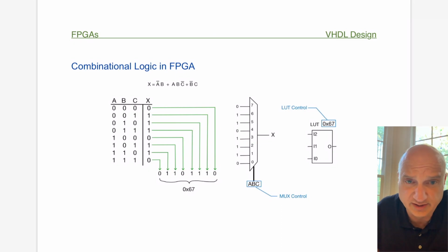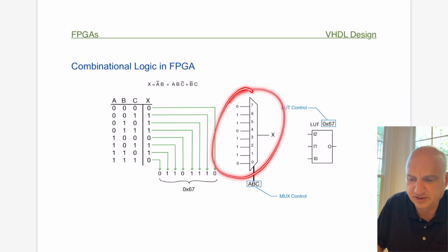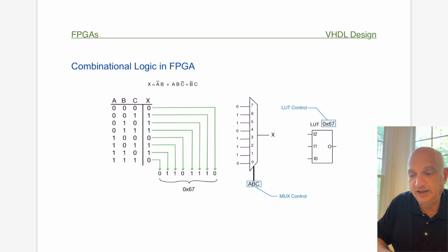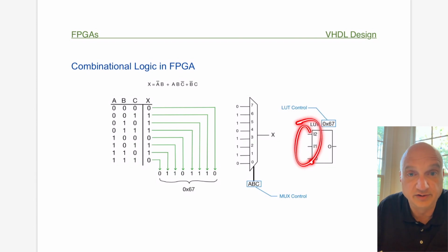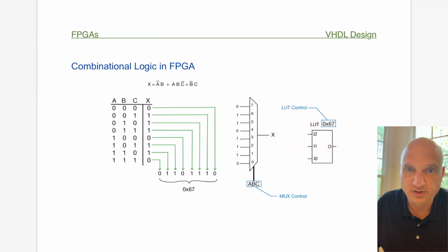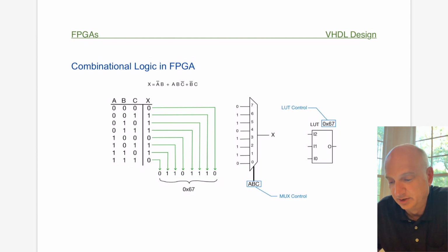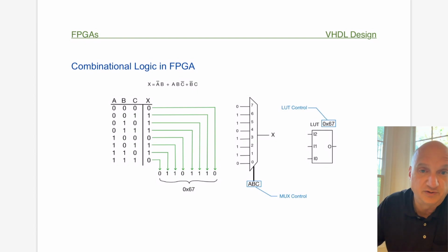So it's really an easy thing to do if you just look at this as a multiplexer. So any logic in 3 inputs can be done in a single LUT like this. LUTs are not all created equal. In fact, the Artix 7 FPGA that's used in the Basys board that we've used in some of our demos actually has 6 input LUTs as part of its structure. So all the LUTs in it are 6 input, and that means they can handle 6 distinct variables as part of the input structure for the LUTs. And so any logic in 6 variables can be done there.